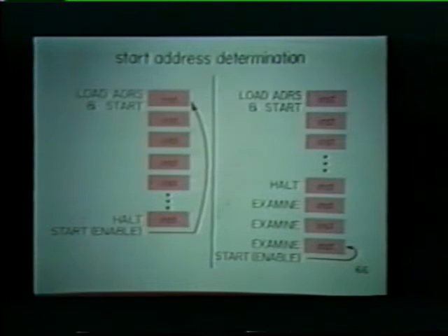Remember when we talked about the load address function? We noted that the address in the SR was sent to a temporary location in the processor when load address was pressed. If start is pressed later, after the program is halted, the address in this temporary location becomes the point where the program is restarted. However, if either examine or deposit are pressed subsequent to load address, the address in our temporary location is changed. Now, if the program is halted and then restarted, the starting point is the last instruction we examined or deposited, not the address from the load address operation.